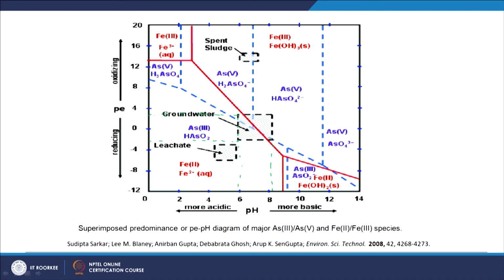Here, as you see, in this region, which form predominates? Arsenic in oxidation state 5, mostly as HAsO4 2-, and for iron, which form predominates? It is Fe(OH)3, the solid. So how does this affect the system? As the solid is formed, or the Fe3+ precipitates at this particular range of Pe and pH, it also allows for co-precipitation of this arsenic 5, which makes sense, hopefully.